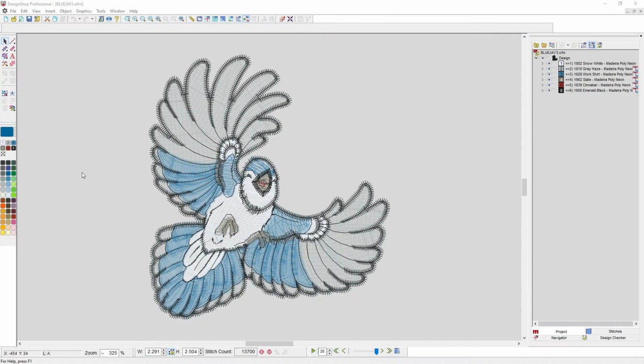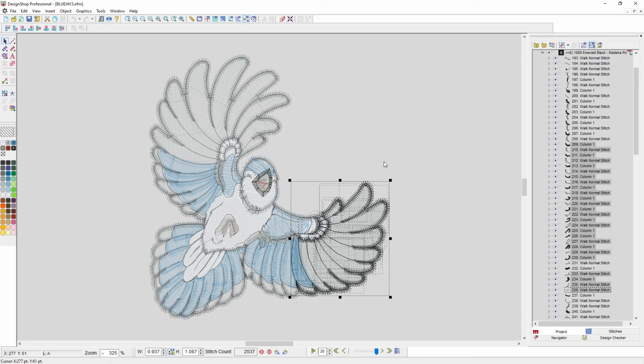Some of those selection techniques may be review. We've talked about them in other videos, but now we're getting into some other selection tools. For example, the custom point selection tool. It's this guy here. This is a little dotted star, and I can click and drag in the view window around elements that I want to select. And then when I hit enter, anything completely contained within whatever I drew will be selected.